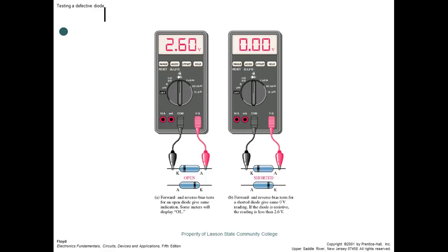So yeah, you'll see them in series. It's not for the current though. Usually when we put them in series, it's for the breakover voltage. So good question. Any more?